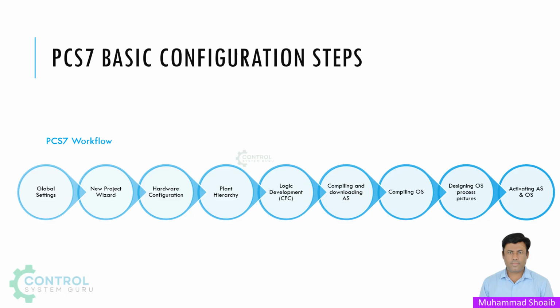In this video, we will learn the basics of project configuration in Siemens PCS7, and we will also learn how to create a first project in PCS7 step by step. So let's get started with the PCS7 basic configuration steps. We'll follow the PCS7 workflow to create a new project. Let's understand these steps one by one.